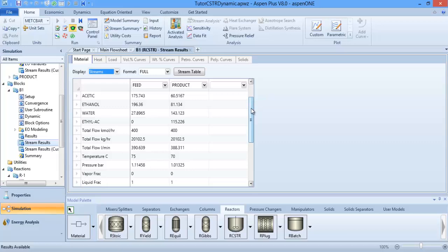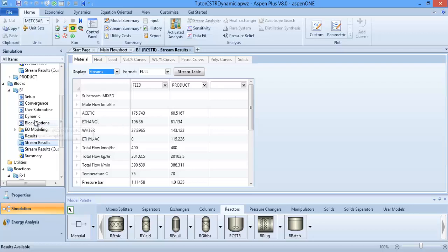Because there can be an increase in flow and pressure, or the flow can continue while the pressure is low, and even the flow may be controlled while there is high pressure buildup inside your system, and that will not be good when there is high pressure buildup and the flow continues. When you take some other study on dynamics and control, you will read up on the difference between flow driven and pressure driven, and we'll get to pressure driven simulation as well. For now, we are going to be using a flow driven process, and we are going to be inputting the dynamics of the unit operation.